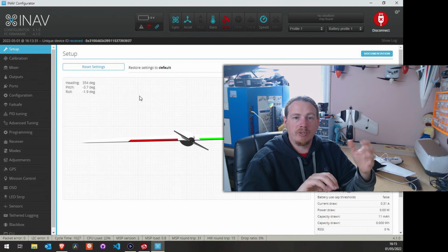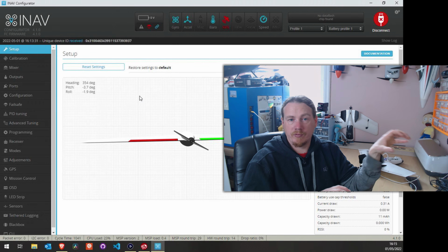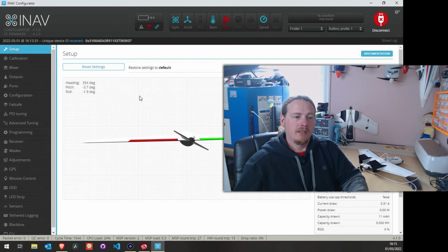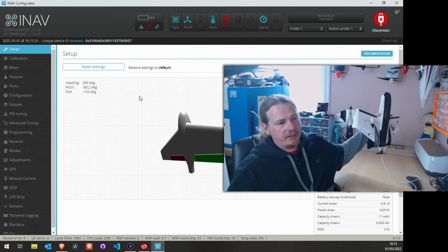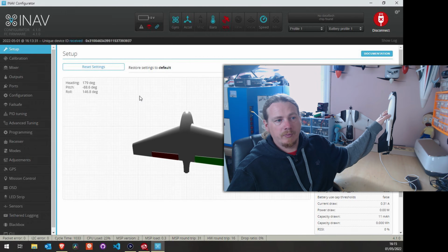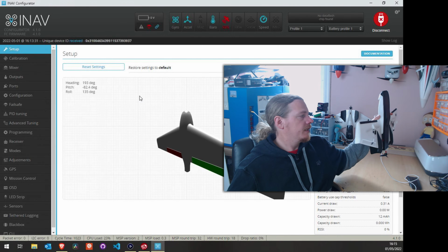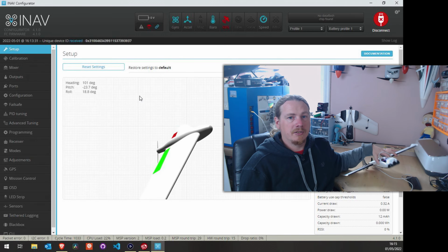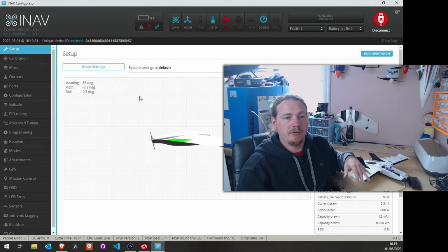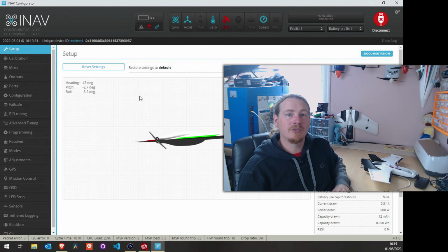Launch throttle is the one that we need to actually work out with the plane or with the calculator. And what we ideally want is to be above the 1-to-1 thrust to weight. So what I'll do is I'll get a battery plugged in, and then we'll jump into iNav and I'll show you how to do it using the spinny motorway.